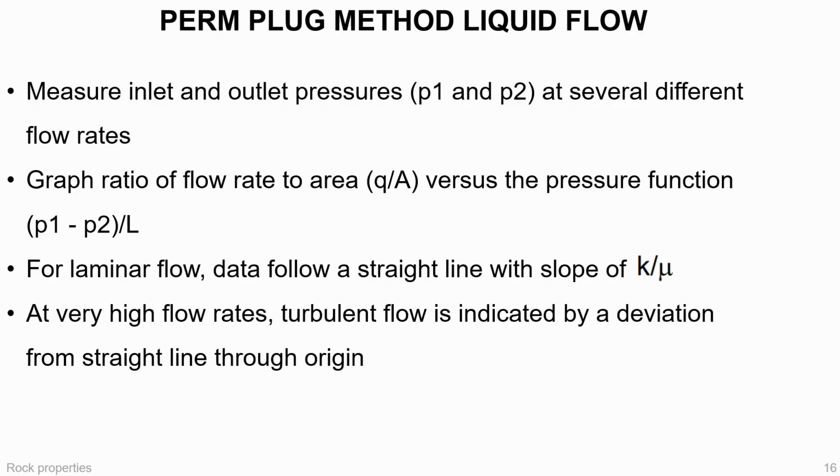However, if the data curve away from linearity at higher flow rates, this suggests the presence of turbulence or other non-Darcy effects. Therefore, permeability measurement should be understood not as a single fluid injection test, but as a control procedure that also verifies whether the correct flow regime has been maintained.